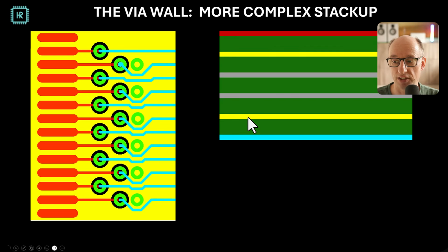Now it cannot get there unless you place vias very close. So this is the solution here. These extra ground vias will make sure that the return current path can move from this ground plane to that ground plane. And if you need to move back from the bottom layer to the top layer somewhere on the right of the board, you'll need to do the same structure in reverse. So this is a way to deal with that.